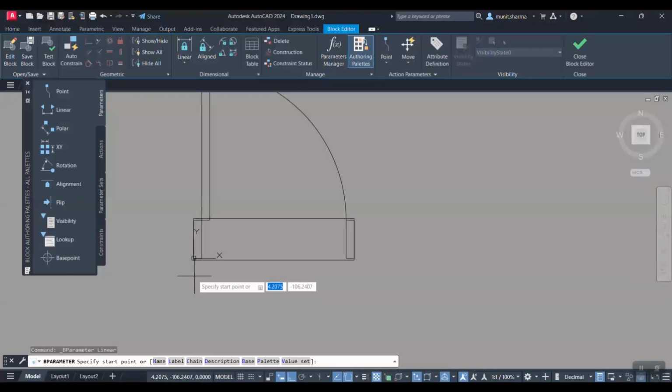So from this corner point, I found that once I place a dimension, you will get a dimension distance parameter here, and that will help me with changing any stuff, right? Any stuff means if I wanted to change something, like changing of dimensions after saving the block, I can do this.